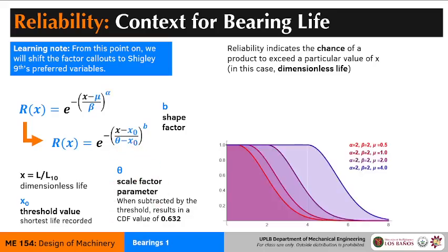And the graph would look something like this. It's the reverse of the failure function. The failure function rises with increasing life. The reliability function decreases, like there's less and less of your units surviving after a particular point. And these are the graphs when you change the threshold value. Again, the threshold value is the first unit that failed. It's the absolute failure of the entire batch, and that's where everything goes downhill. All right, so that's reliability.